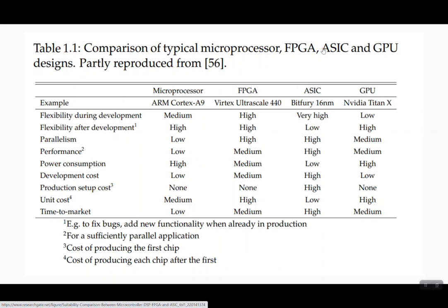When a certain functionality of a digital requirement has been tested thoroughly, and companies want to produce it in mass quantities, they normally opt for making that design into an ASIC, and those ASIC ICs are popular for mass applications.